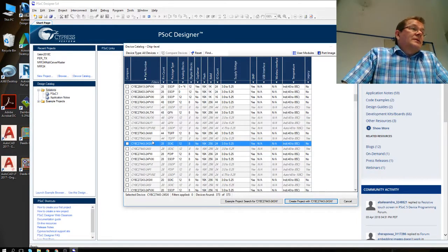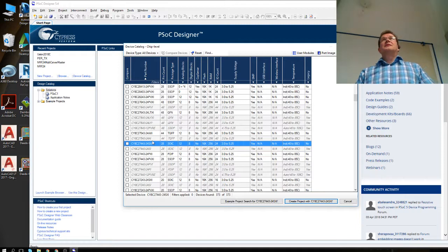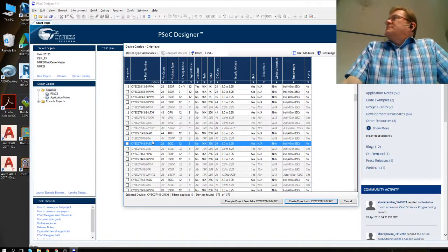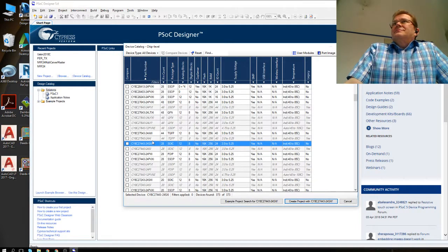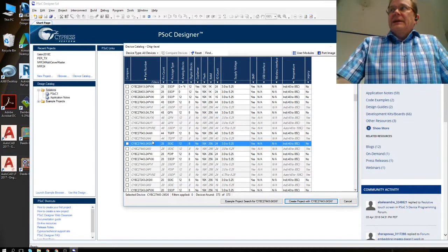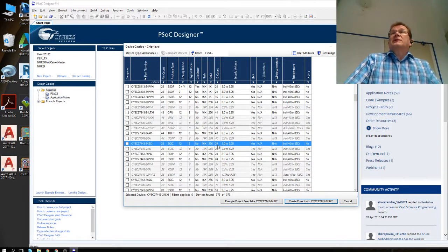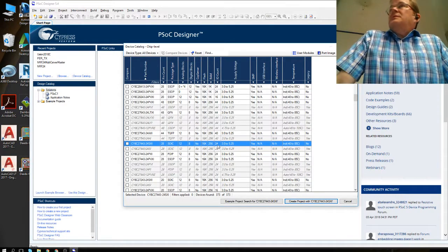And actually, you can also use that flash for temporary space. So there's also a kind of EEPROM simulator or emulator. You can define part of that program memory as normal, non-volatile data memory. Okay, I/O count 24, which is quite nice for a 28-pin chip.